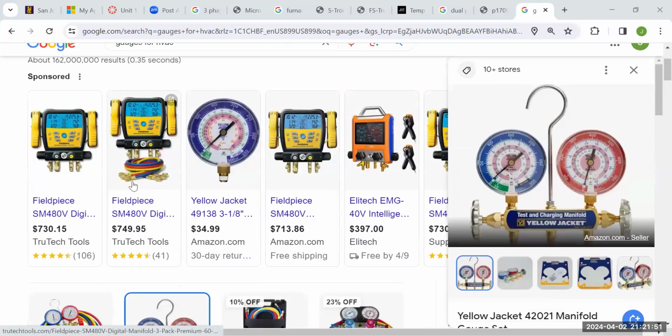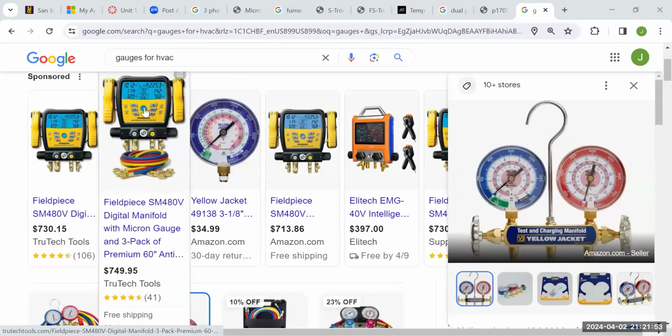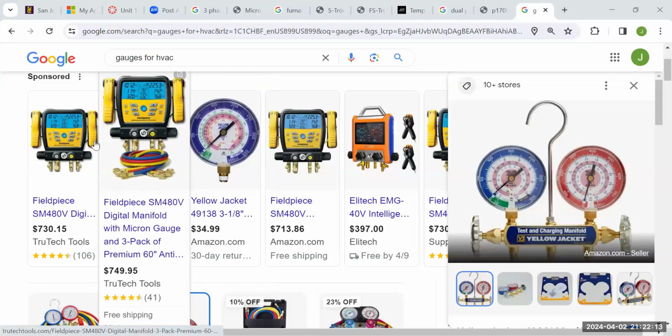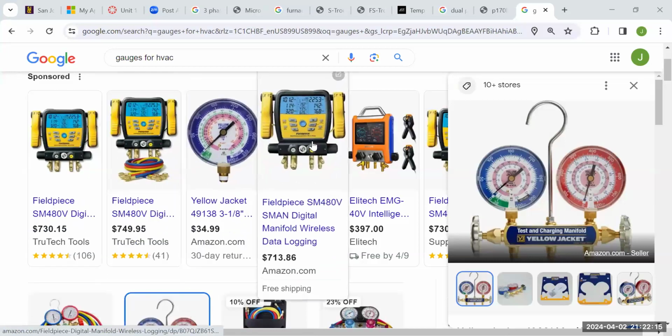And then these nice digital gauges, they have a little button on them that you can recalibrate them. So you'd have to open them up to the atmosphere, so it's sensing atmospheric pressure, and then you zero it out at atmospheric pressure. If you're in the 122 course, start playing around with these nicer gauges. They do everything for you.